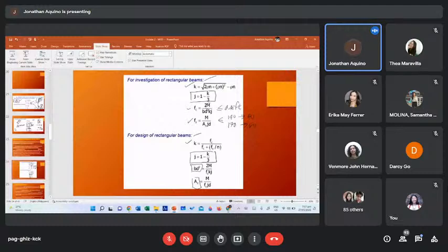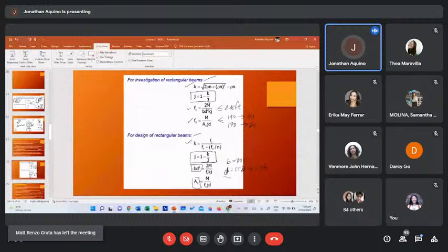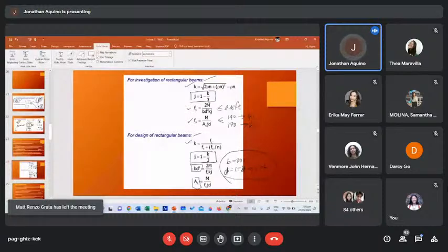Okay? Let's say, for example, 300, or sometimes the ratio is b is 1.5d to 2.5, or either d is 1.5b or 2.5b. So the ratio, the assumption, depends on the designer. Normally, we start with the minimum requirement of the code. The code's minimum dimension of b for a special moment resisting frame.